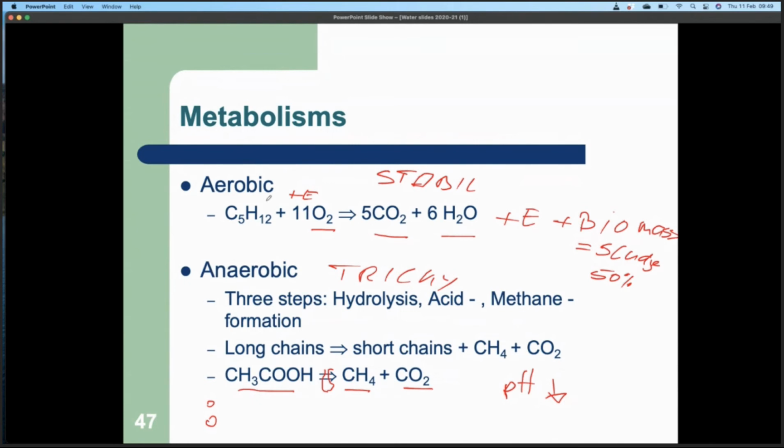Aerobic bacteria are quite happy with this, and you can just switch the blowers on a bit more and give them more oxygen, and they'll just consume it all. They're tough. Anaerobic bacteria don't like this. So that's why anaerobic treatment, even though it looks possibly better in terms of carbon balance, is not normally used in secondary treatment in wastewater treatment works, simply because it is too complicated.